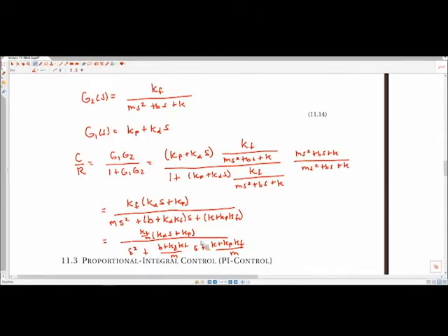We can't change PD, right? So the term that normally determines damping is the S term. We now have the ability to add virtual damping, to augment what was just natural damping in the system. And so that's the main benefit. We'll talk about other benefits too in terms of stability. Damped systems are usually very stable, but that's the main benefit. That's why the derivative term helps here, because it adds virtual damping to the system. So this adds here.